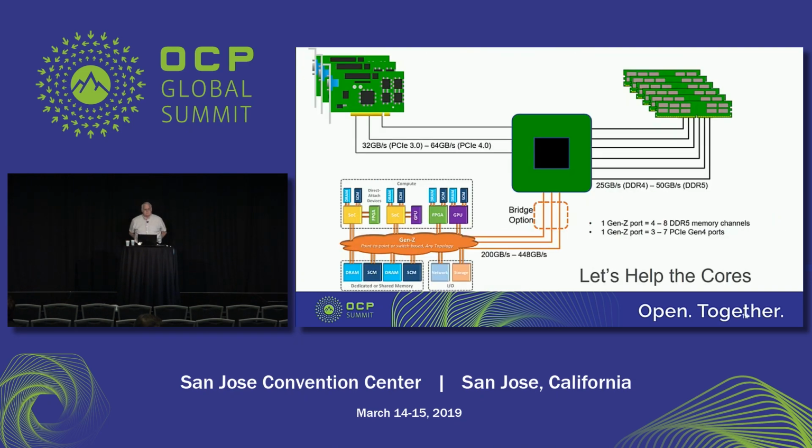We go a little bit further into the architecture. The top is reminiscent of our current situation where we have PCI buses coming off our processor to the left, the standard PCI add-in boards. Off to the right, we have DDR modules using standard DIMM modules. In this picture, we draw our vision of where Gen Z would intercept at first.